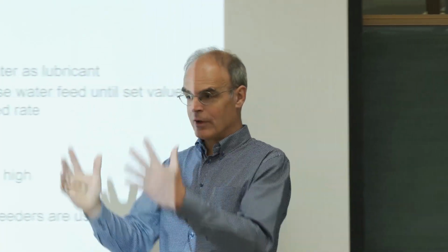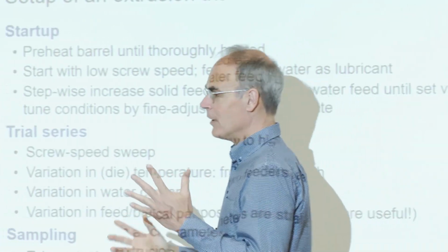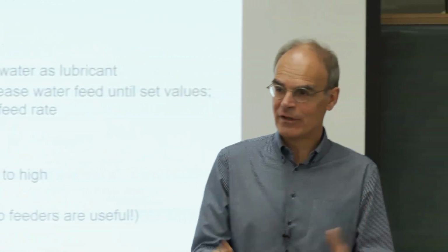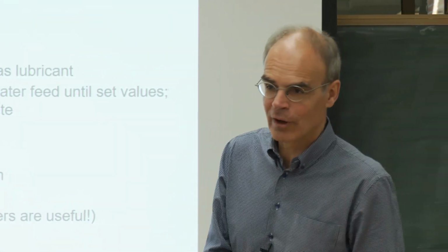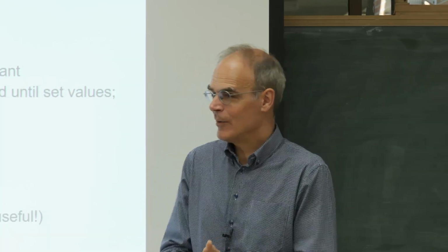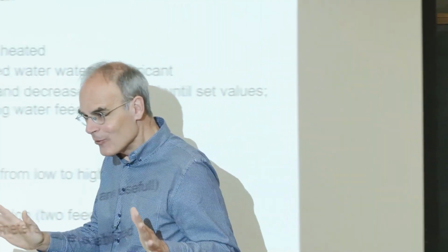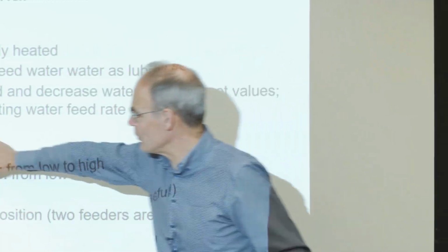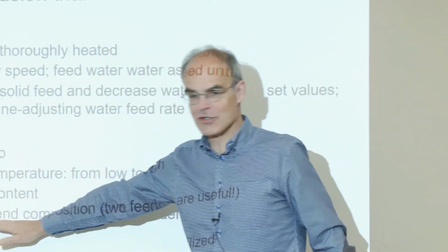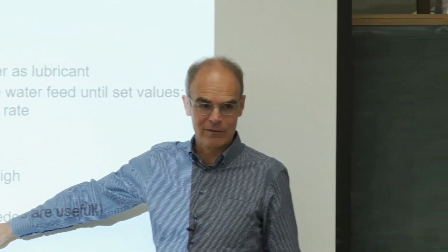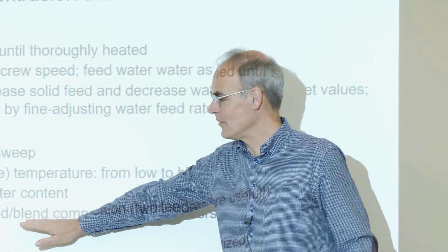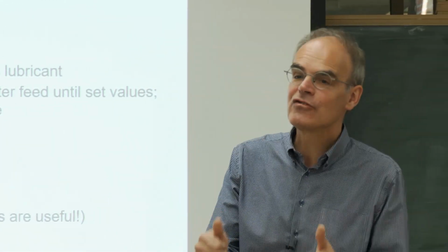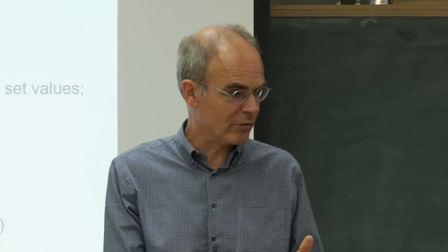You don't want to stop your extrusion, empty out that feeder, clean it, put in a new one, and restart, because then you can maybe do one or two trials a day. That's not very much. So do all these easy parameters before you start thinking about that. If you have one feeder, that's where you actually are. It's really tricky to manage the changeover.